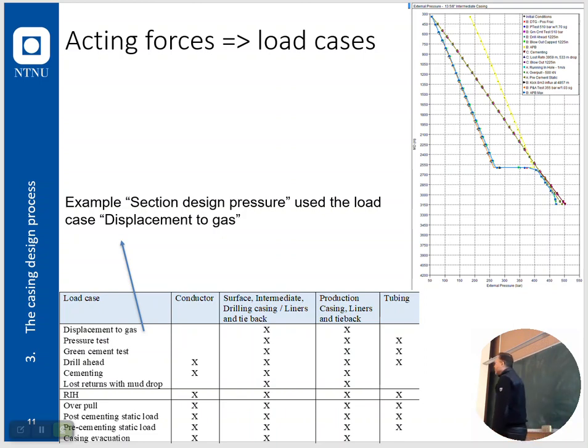There are two things you need to know and take away from running hole. One would be, well, let me ask you guys, what do we need to concern ourselves with when running hole? And it's not really part of the casing design software, but yeah, surge pressures, very good, thank you. Surge and swell, right? And remember the difference between a floating rig that goes up and down all the time and a fixed one.